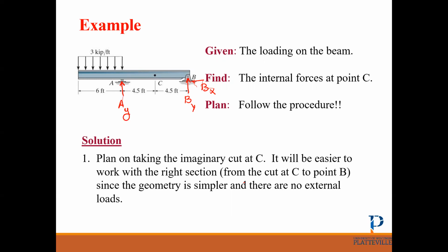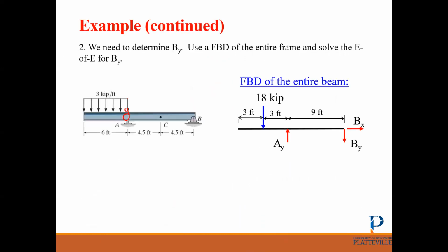All right, so what is the next step? Just draw a free body diagram for the part that we want to find internal forces for. Okay, so I decided to draw the free body diagram first and then find the reactions. So the first step, find the reactions. Go ahead and stop the video and find all the reactions at Bx, By, and Ay.